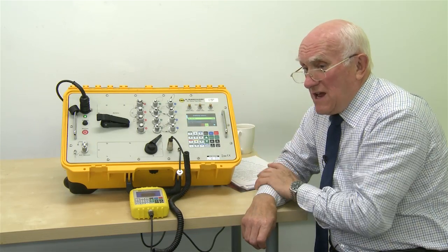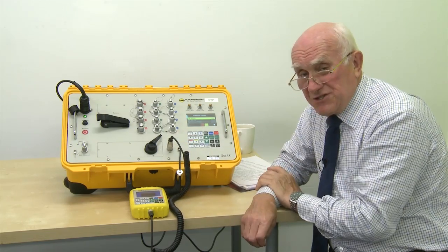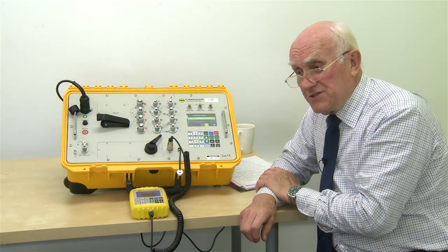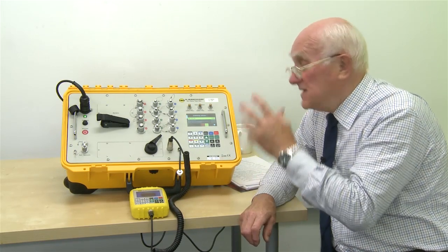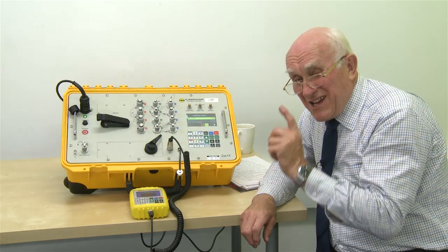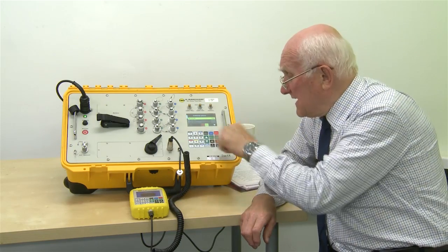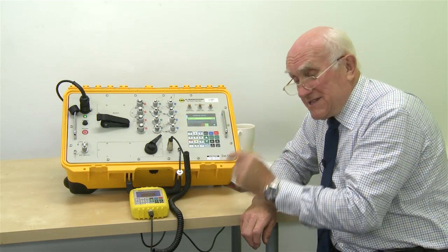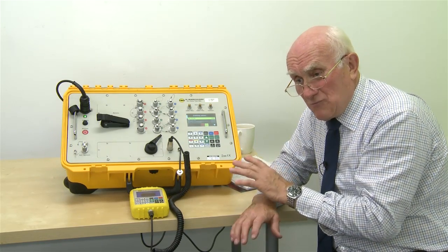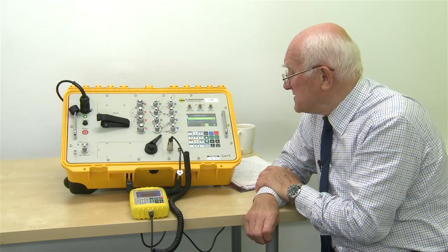when you switch the instrument off at the end of your testing, those limits you've just entered will be forgotten, and next time you start up, you will have the situation where the previous factory-fitted limits apply. You can change them permanently if you wish, but we don't allow that via the front panel. It tells you how to do it in the calibration manual, because that we feel is a different supervisory level to do that type of exercise.